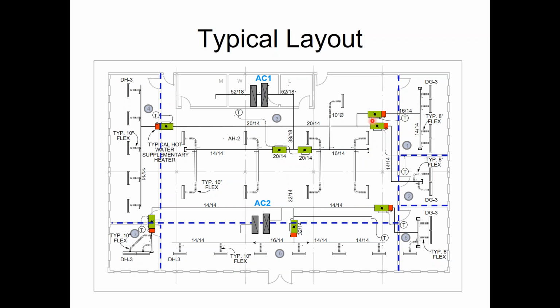So what this allows us to do is that if these interior zones want cooling, we can run the air handling system in cooling. And if one of these zones calls for heat, we can throttle his damper back to some minimum position and then turn on his auxiliary heater. And now I can handle simultaneous heating and cooling. My rooftop can't do it, but I could do it by adding, in this case, 3 heaters here on the perimeters. Now, if these guys didn't want very much cooling or didn't want cooling at all, they were satisfied at the moment, then I could run the gas heat on the rooftop and turn off these supplemental heaters and let this guy take care of the heat.